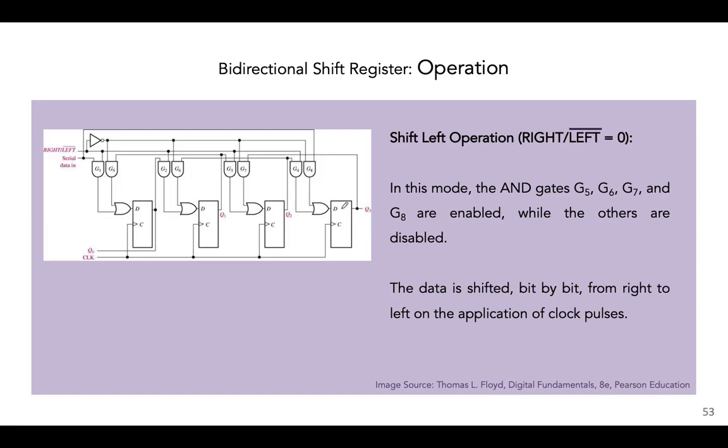So see now, whatever bit was in this flip-flop, because this is a feedback network, right? So you can just move on. G7 is open. It'll just move on here. Whatever bit was in this position can simply pass through this flip-flop, go to this point. Whatever bit was in this position will go from G5 to this position. And what have we done? We basically just shifted the data from right to left.